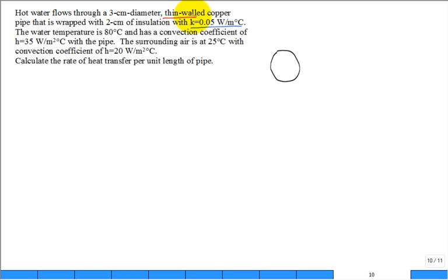So there's no resistance to heat transfer offered by the copper. If I was to say, here's the center line of the pipe, and it's running down that way, this goes out to an r1. So what is r1? It's the same as the inner radius or the outer radius of my copper thin-walled pipe or tube. So what is r1? I know this is trivial, but I've graded a lot of exams. The information's here. I'm going to pause and walk around and see. You write down what is r1 and then what is r2.